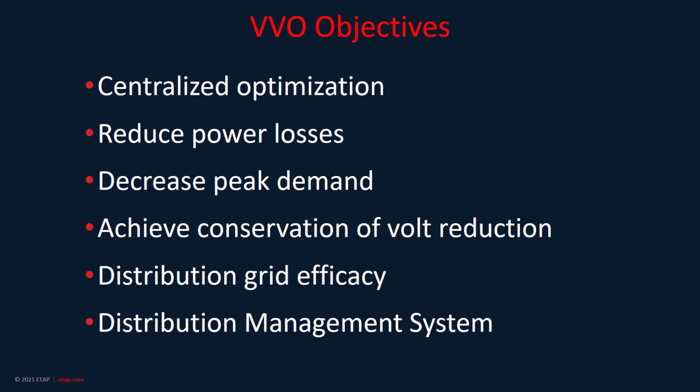The objectives of this particular analysis module, VVO, are to maintain voltage within limits, minimize voltage drops, optimize power flow, real and reactive, reduce losses, improve power factor, optimize transformer fixed taps, load tap changers, and generator set points, and minimize component or circuit overload.